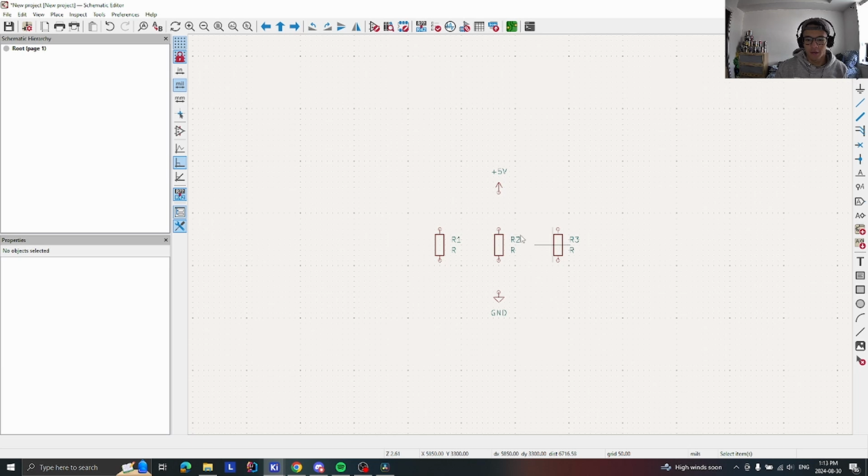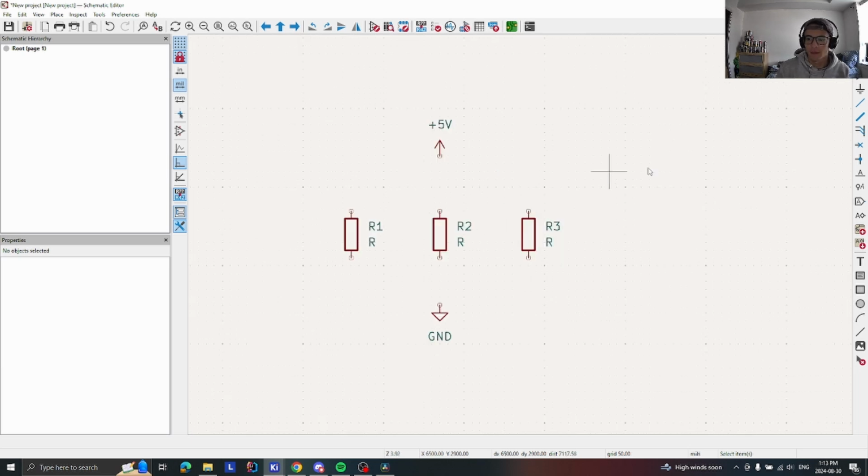So now that we have these basic configurations, we can go ahead and connect them. And you can do that by clicking this wire here and clicking the terminals and connecting. The other way you could do it is by clicking W and left clicking. I personally like to use W, it's a lot quicker. Just like that. And one thing you're going to notice is when you're connecting components, you need an end terminal here.